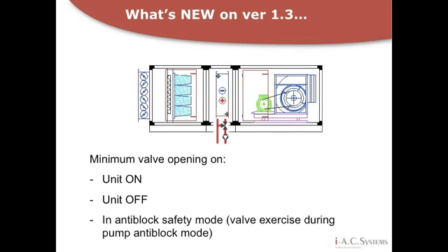In anti-block safety modes, on the previous software version, Carel had introduced the management of single or twin pump sets for each water coil. In the management module, the user has the facility to enable an anti-block function where on every 7 days of inactivity, the pump will be enabled to run for 30 seconds. In software version 1.3, this operation has been extended also to the water valve. This is also called a valve exercise.